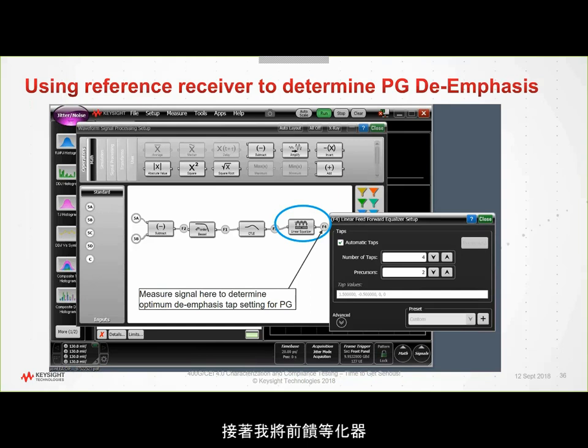And then what I did is I added the feed-forward equalizer on the receive side, okay? Now, since it's a linear system, I can put that equalizer anywhere. In theory, I can put it on the receive side or the transmit side and have the same effect. In actual life, even though it is a linear system, there is a little bit of difference because of where the noise is in the system. When you put the FFE on the receive side, you're going to be working on the noise that's in the channel as well, whereas on a transmitter, it doesn't have that noise.